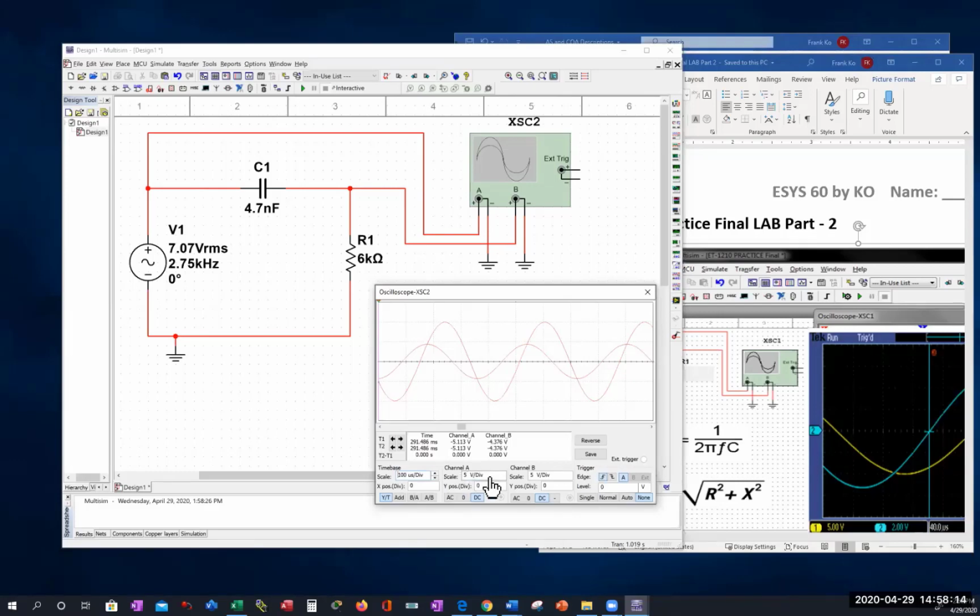No, so it's 2 divisions. Hey, that's right. Remember, right here's your scale. We've done this some weeks ago. We have a vertical scale that tells you each square is worth 5 volts per division. And if you look at this, here's a square. From the 0 line to here is 1 square. From this square is another square. So if you look at this one right here that my pointer is pointing at, from the 0 line, I have 1 division, 2 divisions.